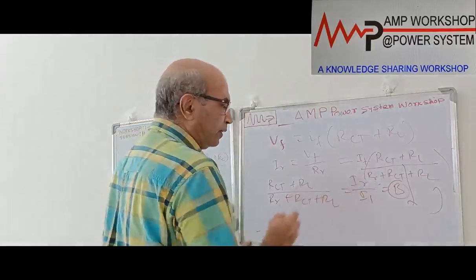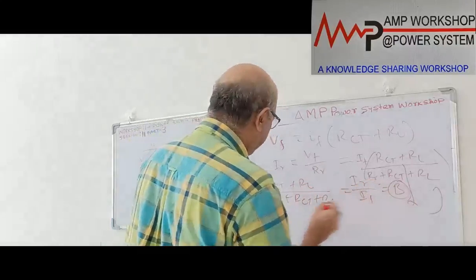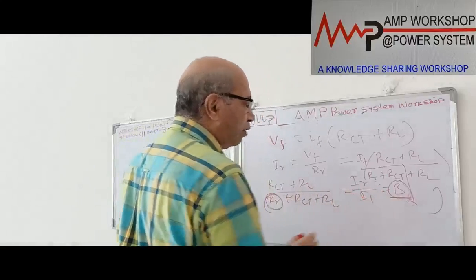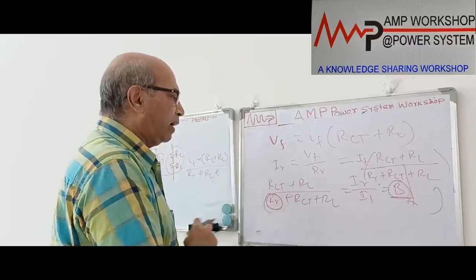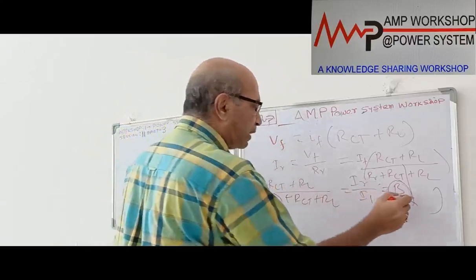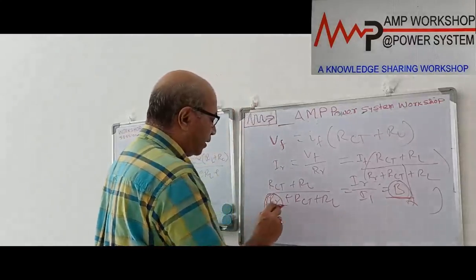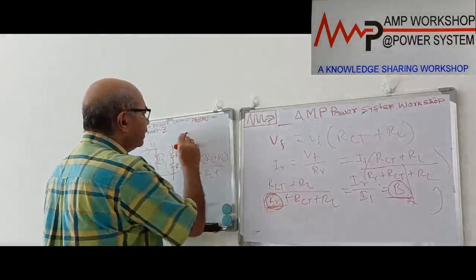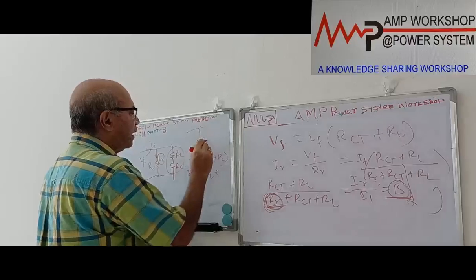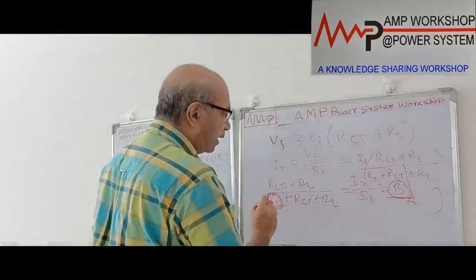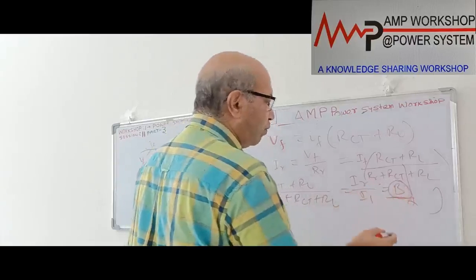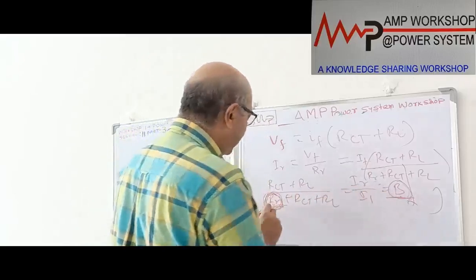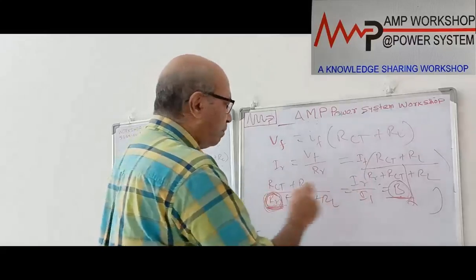So if this is the case, then you see this bias factor depends on the resistance. As you increase the resistance, automatically the bias will be reducing. That means the relay current will now be less. The bias factor changes as you increase the relay resistance, because it depends on the relay path. We have shown the relay path. This is the relay path, relay is connected over here, that is RR. So relay resistance is also a factor of B. If you want to increase B, you have to reduce the relay resistance, and if you want to reduce B, you have to increase the relay resistance.